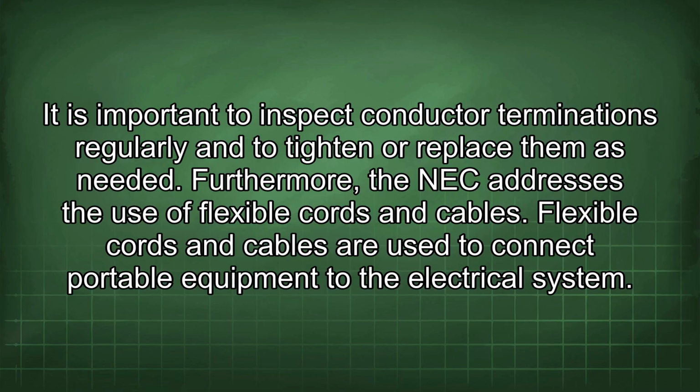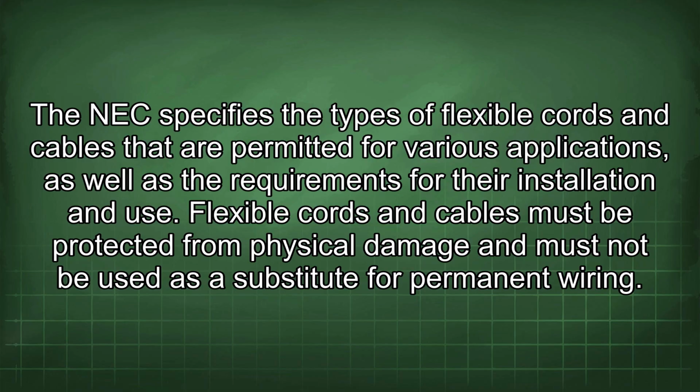Furthermore, the NEC addresses the use of flexible cords and cables. Flexible cords and cables are used to connect portable equipment to the electrical system. The NEC specifies the types of flexible cords and cables that are permitted for various applications, as well as the requirements for their installation and use. Flexible cords and cables must be protected from physical damage and must not be used as a substitute for permanent wiring.